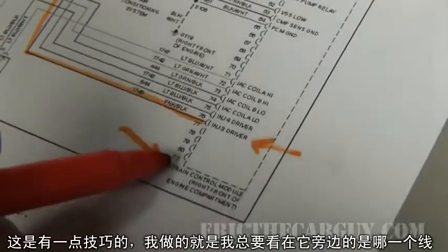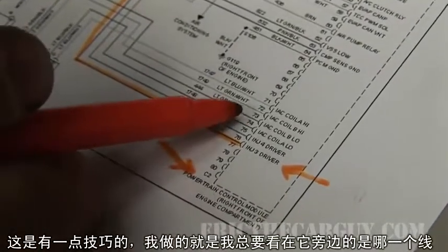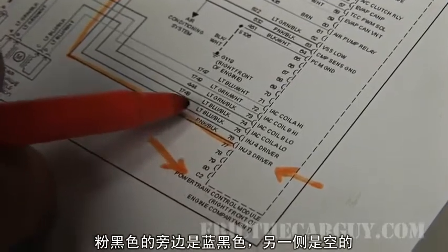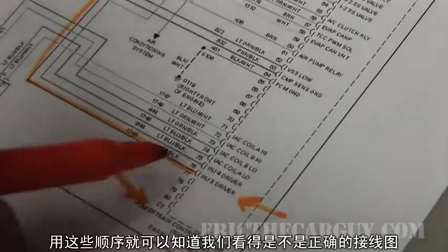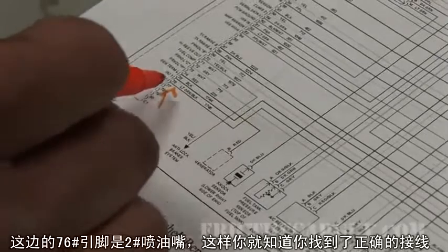Now this can be a little bit tricky to identify on the computer. One of the things that I do is I always look at what is next to that wire. It's pink and black. Next to the pink and black is a light blue and black, and next to that on the other side is a space. I use that sequence to let me know that that is the correct wire, as opposed to if you come over here and go on pin 76 on this side, which is actually injector number 2. So I go by numbers, which are sometimes hard to see, and sequencing on the diagram to help me identify.